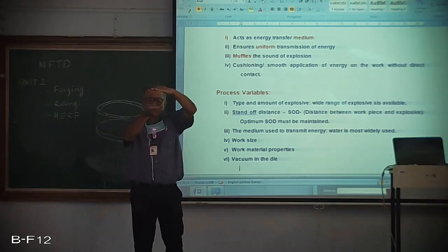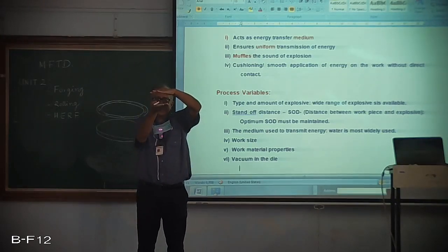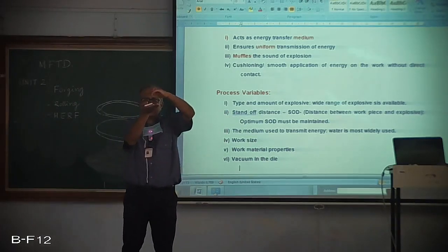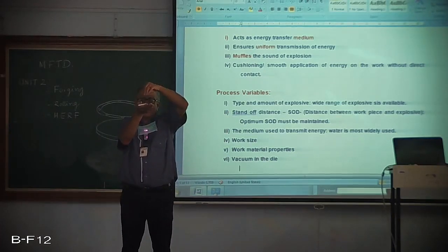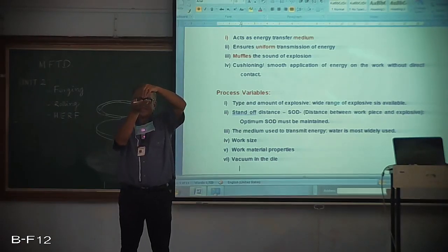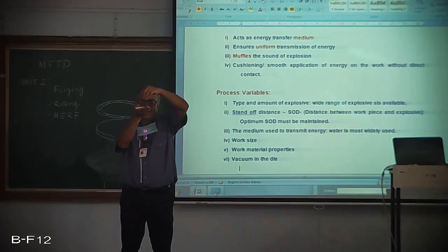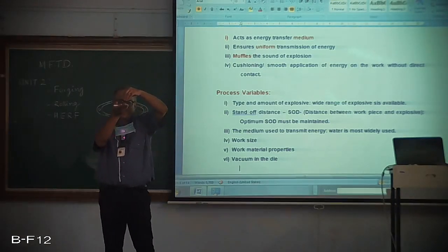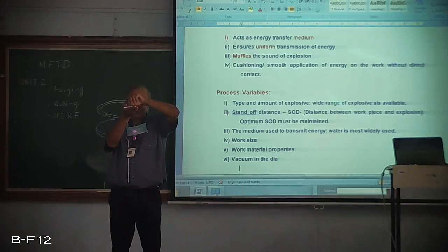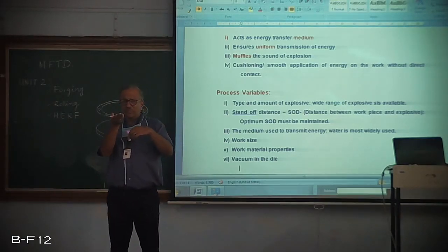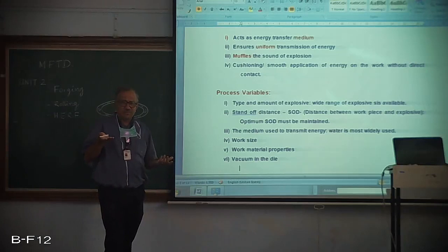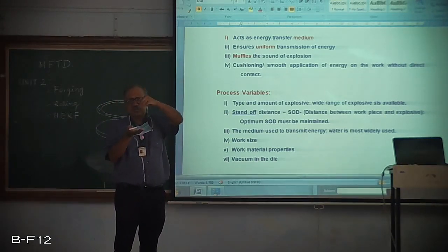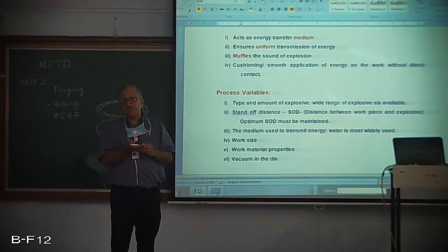At the same time, if the standoff distance is less than optimum, if the charge or the explosive is kept very, very close to the workpiece, then the problem is that in the initial milliseconds, the application of energy is going to be so large and so high due to transient waves that at certain locations the deformation may be non-uniform.